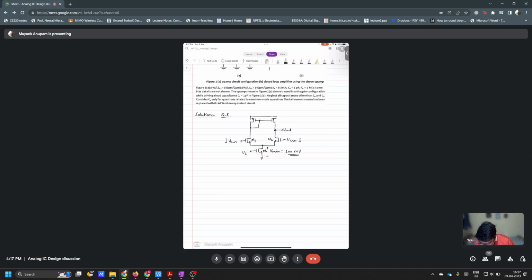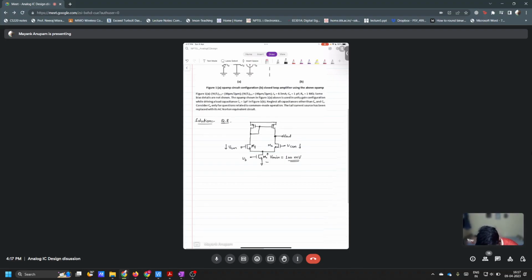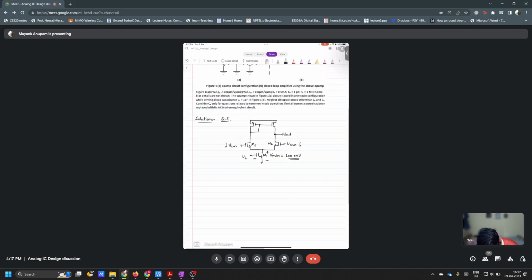Sir, VGS will get affected. VCM is getting decreased, so VGS will get affected, sir. Which VGS? This VGS or this VGS? Both, sir. VCM is getting decreased. So which VGS are you talking about? Are you talking about VGS of M1, M2, or are you talking about VGS of M0?